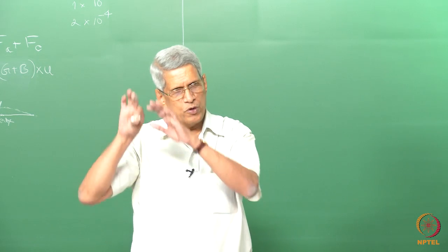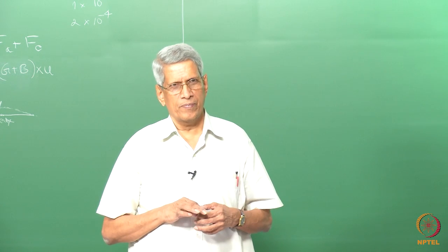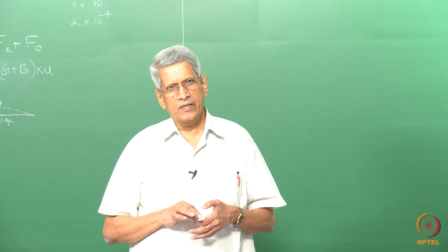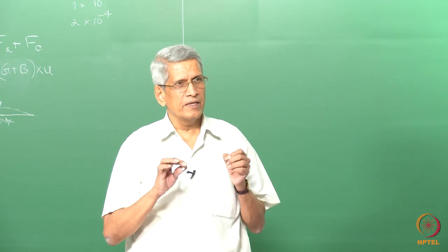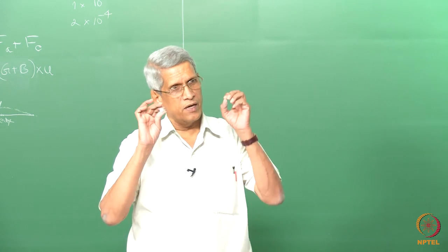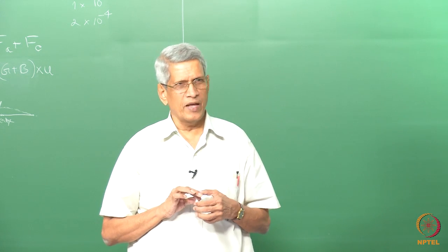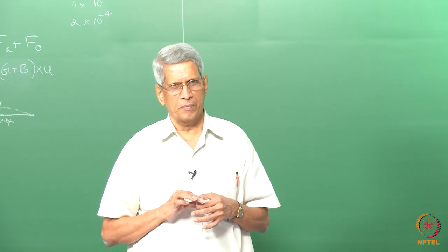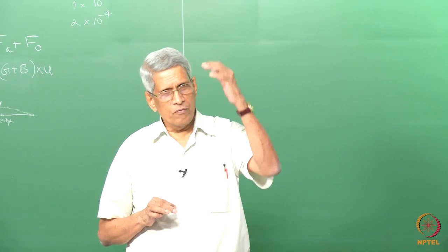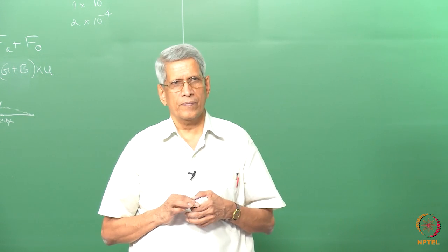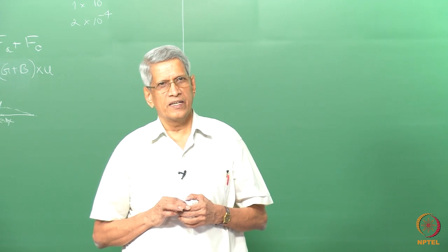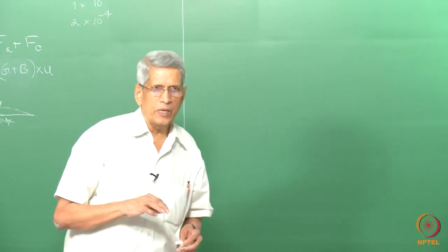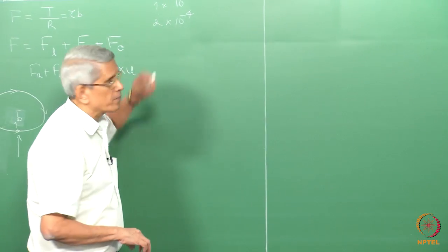Then we quench the material most of the time to retain the high temperature microstructure. That's what is normally done by a solutionizing treatment. When we do this quenching, what will be the vacancies which are generated close to the melting point? It is of this order.